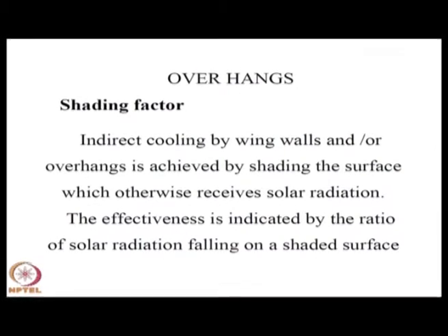So, you calculate as usual your utilizability, and 1 minus phi bar will be unutilizable multiplied by your HT, which will be the energy that will be going into heating the room to the desired level of, let us say, 20 C.